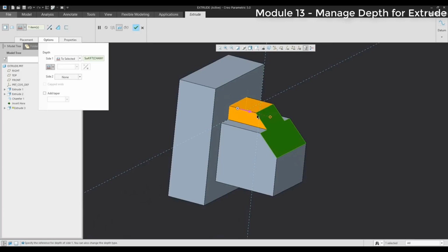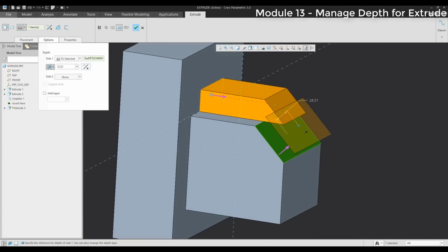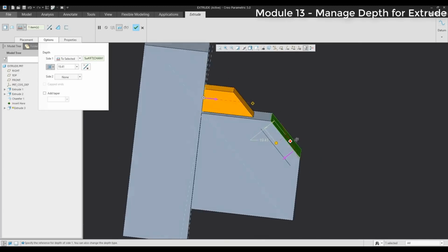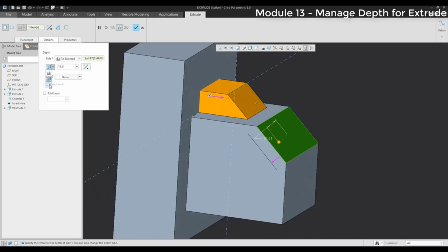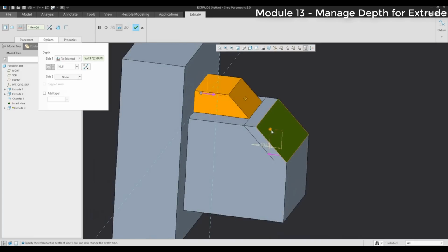The system automatically continues following the selected shape, and here you can specify if you would like to offset from the selected surface, and the system will automatically measure it as an offset, or you can use the function as an Extrude for translation, and you can specify the number of the offset in the selected reference, for example 25.